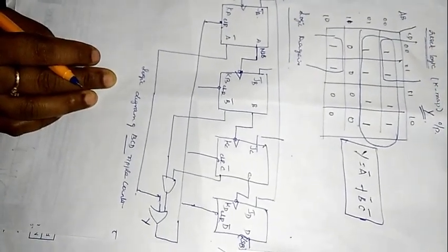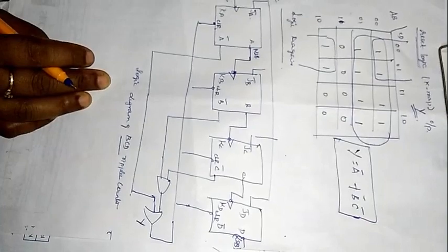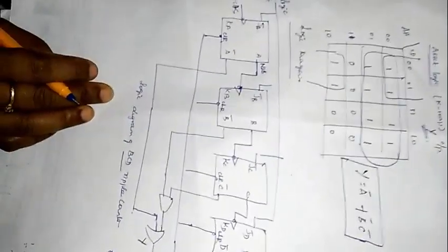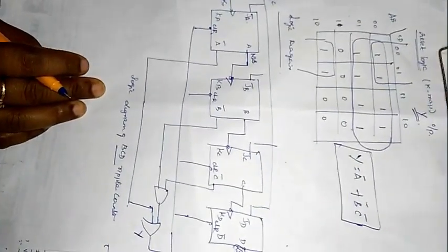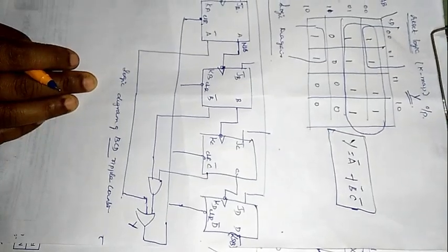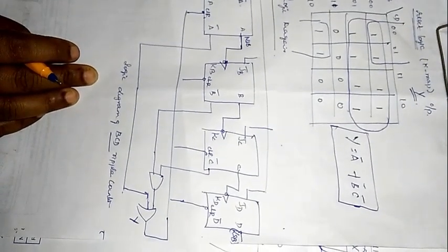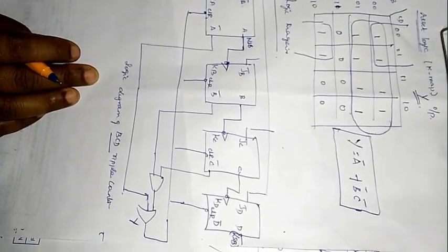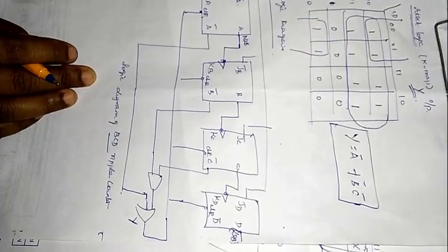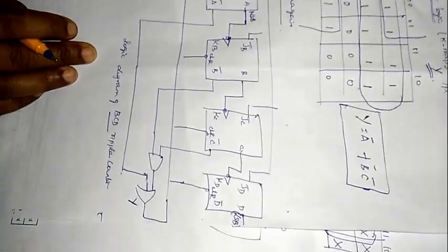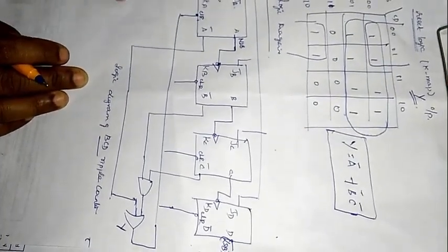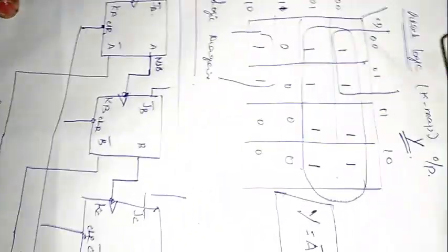This is having the number of states 10. Okay, if I ask you to design the ripple counter of, say, 6 states, then the valid states of counting will be from 0 to 5, and states 6 and 7 will be invalid. So you will assign a 1 only for the states 0 to 5. The remaining 6th and 7th states you will consider as invalid states, and the rest of the procedure will remain the same. I think hopefully you have understood the design of asynchronous ripple counters.